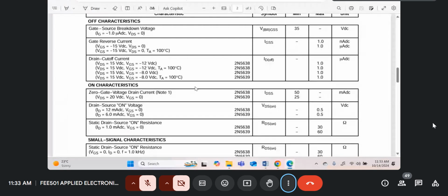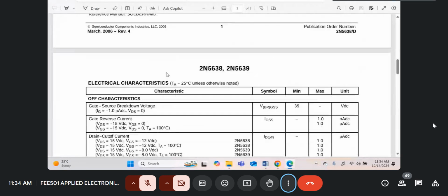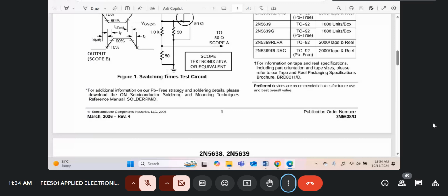I remember there's a transistor we found. Oh, that was a Texas Instruments. Like this on semi, to switch the drain off for various values of VDS, the smallest voltage I'm getting over here is minus 8 volts. So you've got to select your transistors very, very well.